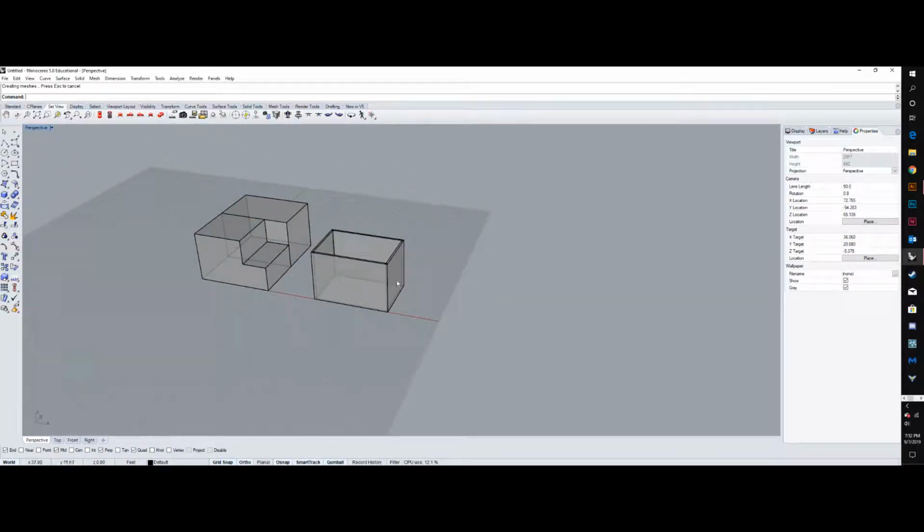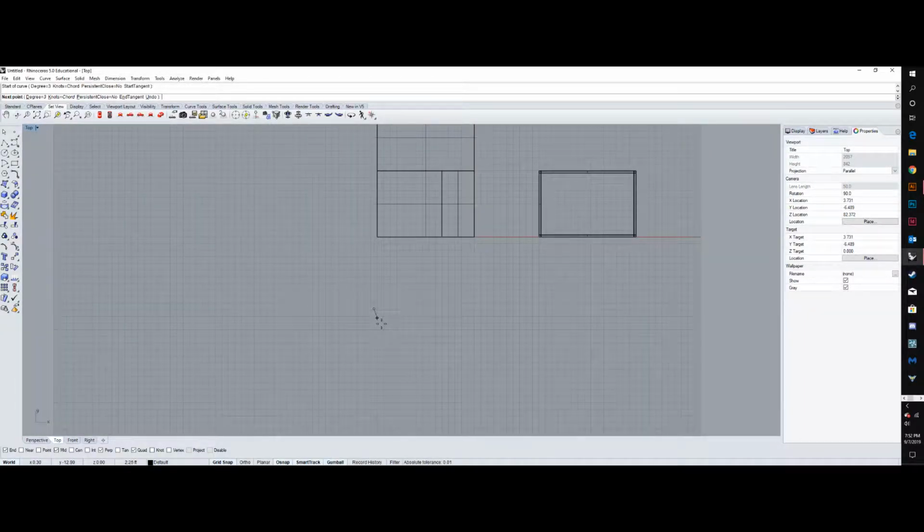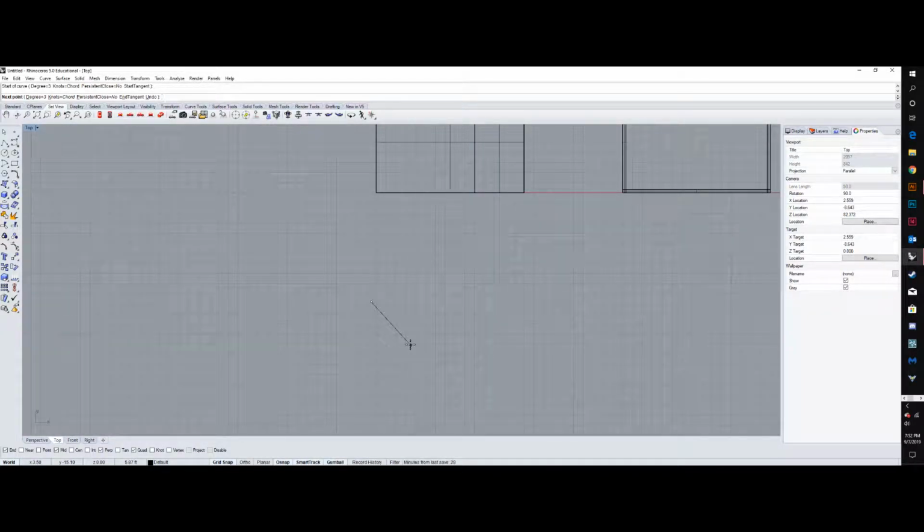Okay. This command also works from curves. Say I have a curved wall. Let's do a really curvy wall. I'm going to turn off ortho in this case, and I'm going to go to my top view. Top view is the best view for drafting 2-dimensionally. Let's say we want to have a wall that looks very, very abstract or nondescript.